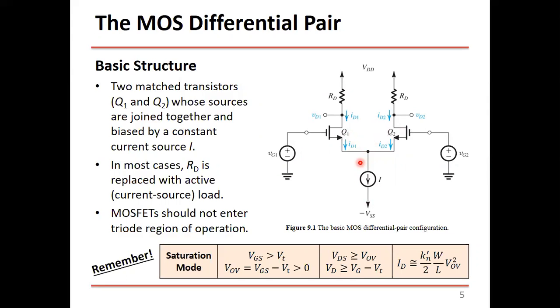Okay, so now we learn how to bias. Instead of having just VDD or VCC and some resistors, we can bias the transistor through a current source, as we learned in the previous topic. You also bias the drain through RD, or, as we're going to see later, you can replace RD with a current source as well. As we mentioned in the previous chapter, it's preferable to use current sources instead of resistors. We try to avoid resistors as much as we can in IC fabrication.